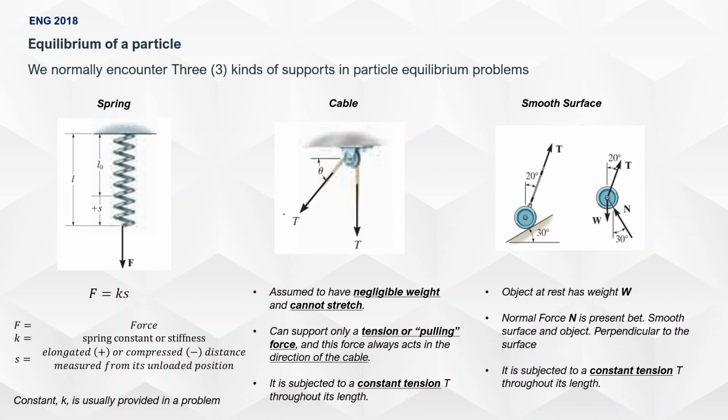Hence why the representation here is the same variable, because whatever the tension being felt here transfers directly to the other side as well. Okay? And then from here, you can now get its respective Tx, respective Ty, and then you just use the angle here to get its respective xy components.